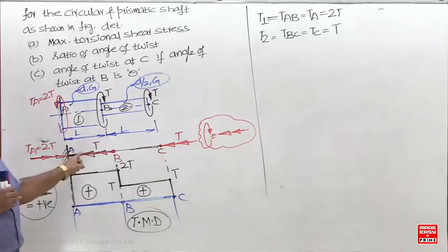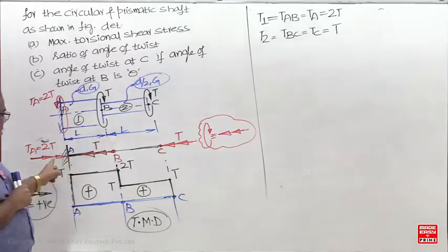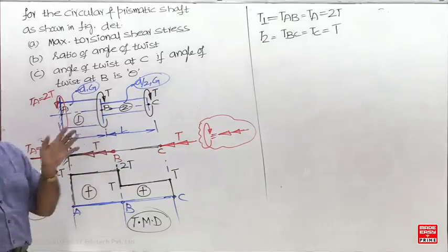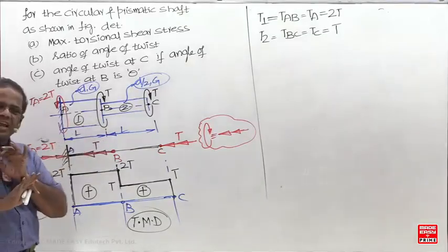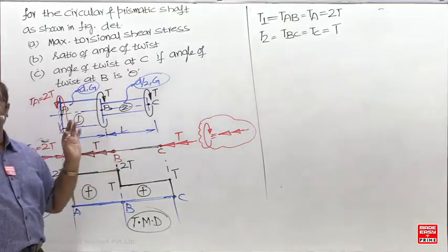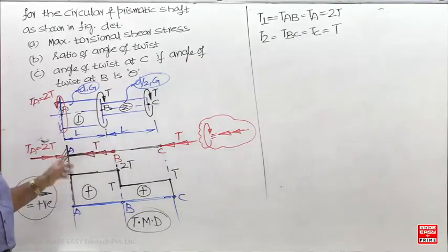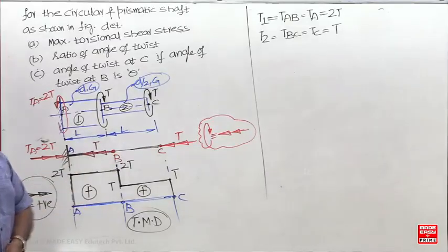So once you convert into double arrowheads, the problem has the same procedure. The only difference is, when you are calculating the axial load, away is positive, but here towards is positive. And the other one is, in place of P by A, I have to use T by Zp.